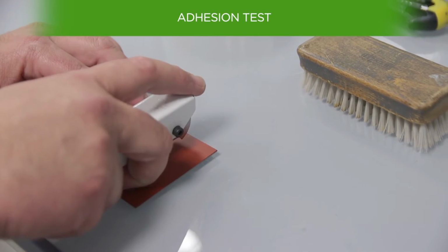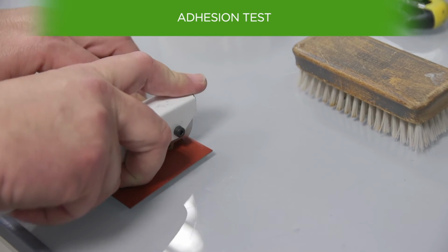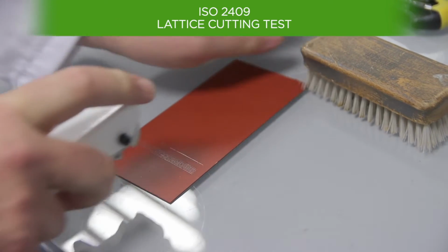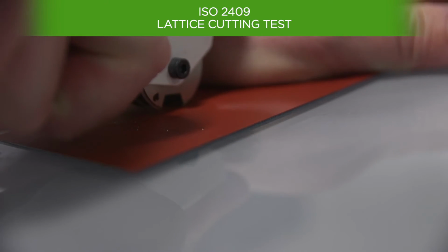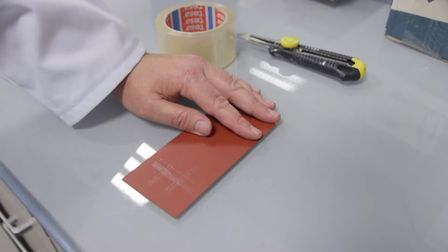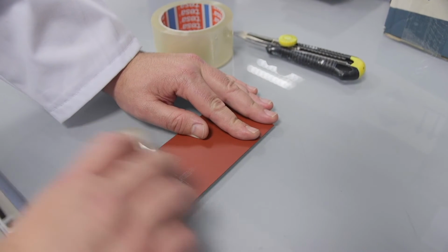Adhesion test. There are two types of test under two different standards. ISO 2409, lattice cutting test. It consists of making two crossed cuts with a comb that has a special blade. Depending on the thickness of the film, we will use one blade or another.